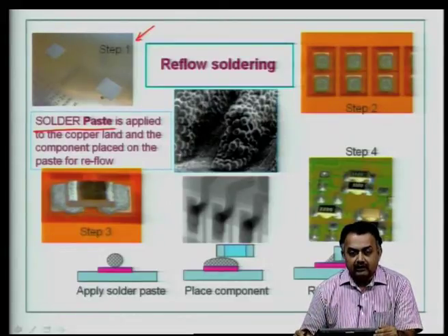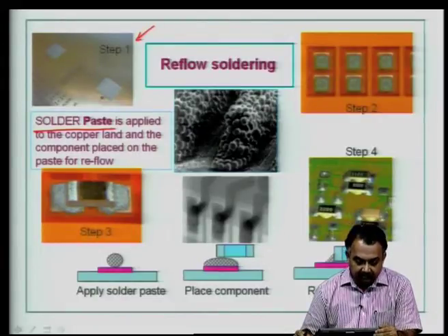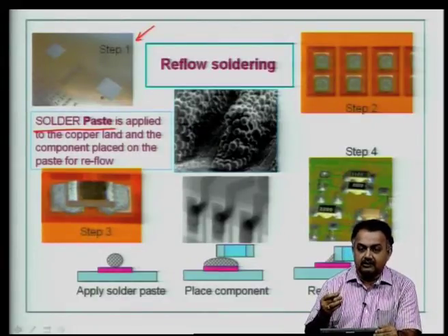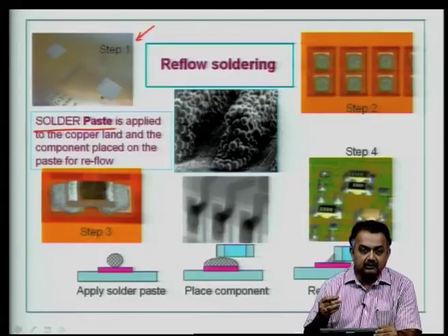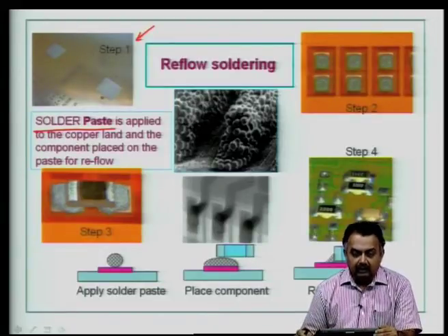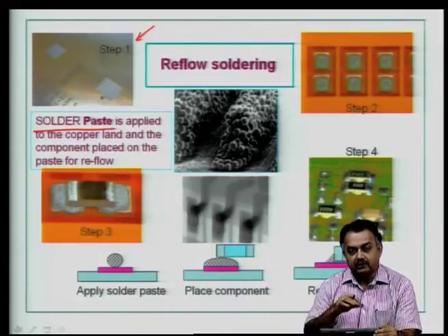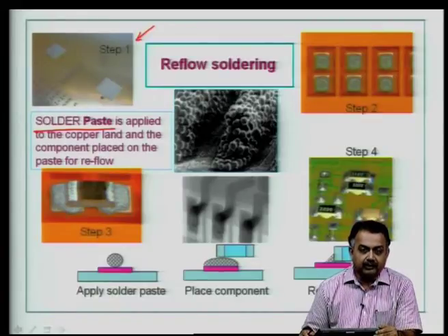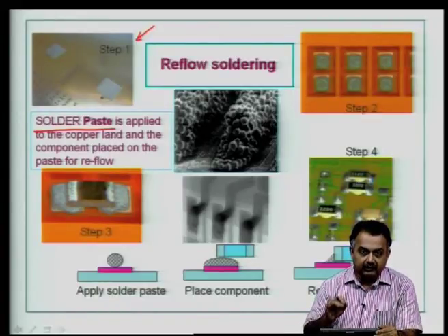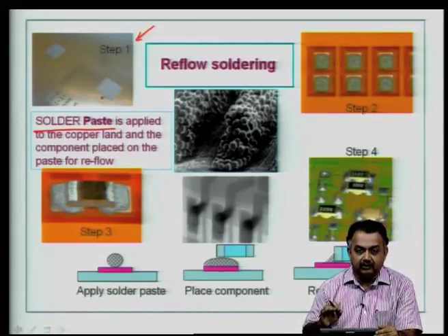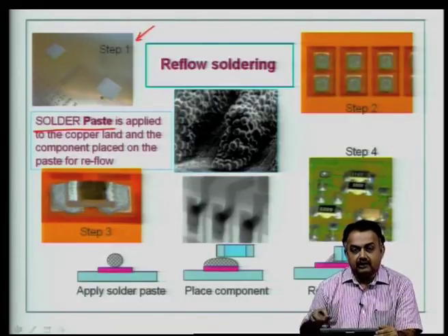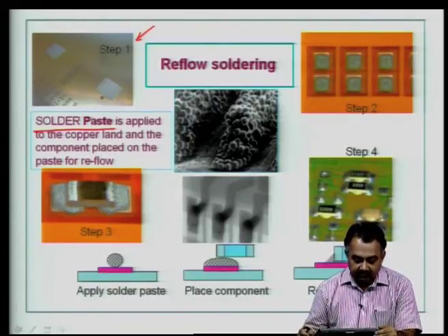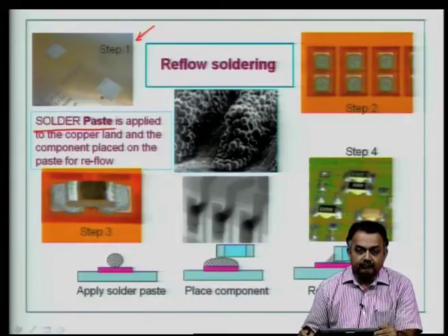If you can recollect, solder paste is a material that contains solder particles, very fine, powdered metallic particles, and they are actually dispersed in an epoxy media, a polymeric media, which contains a binder, which contains some kind of a glue, and in addition to all these components, it contains also the requisite flux material.